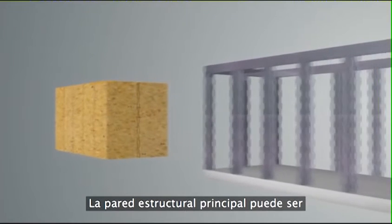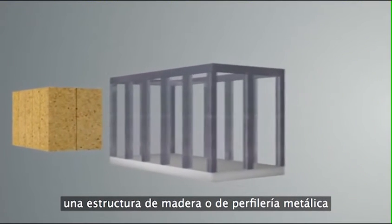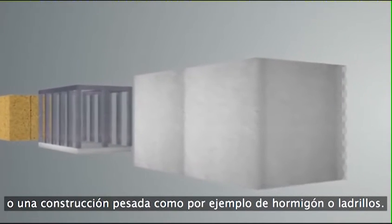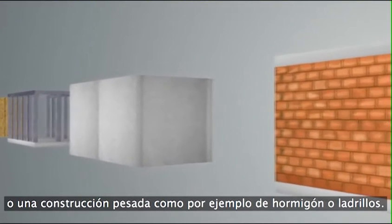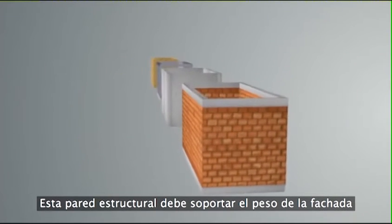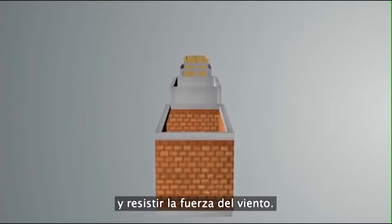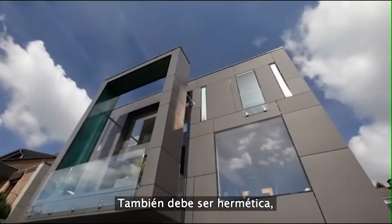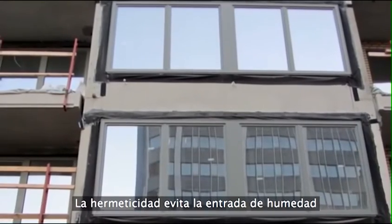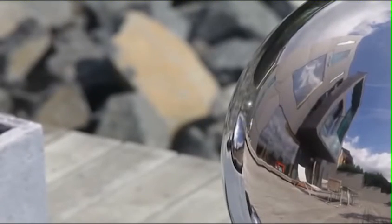The main structural wall can be a timber or metal lightweight frame or a massive masonry construction, such as concrete or brick. This structural wall needs to carry the weight of the facade and resist the power of the wind. It should also be airtight, especially around openings such as windows. Airtightness prevents moisture ingress, and ensures that the building remains thermally efficient.